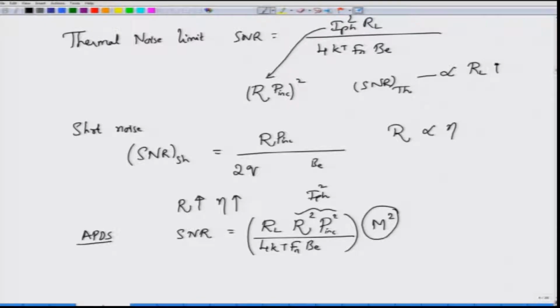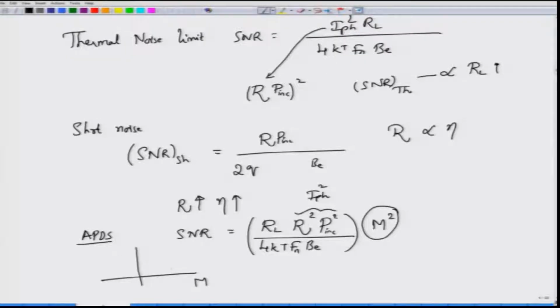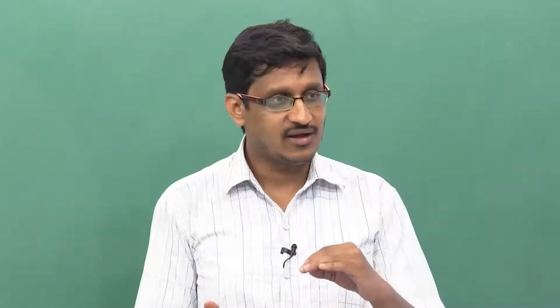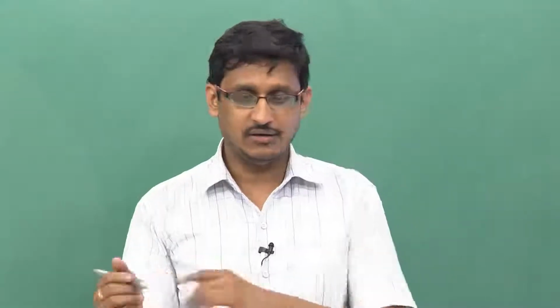which is impacting over here. So, if you want to increase SNR, you can increase SNR by operating the APD with a larger multiplicative gain. However, larger multiplicative gain also has some effect on the excess noise factor F, right, because we have seen that F versus M curves for an APD depend also of course on the additional factor k, but in case you look at it, they are actually linearly increasing for larger value of k. So, there is actually an optimum value of the multiplication factor M, which makes the SNR highest. For a given optical input power, you can maximize this multiplicative gain, which you can obtain by going back to the shot noise variance and then differentiating that with respect to M and setting the resultant expression to 0.